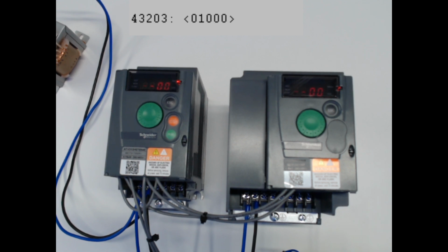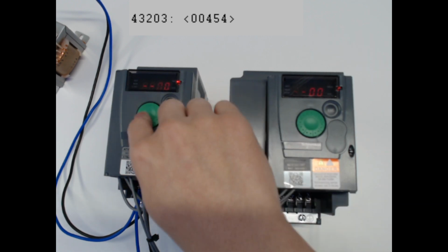Okay, so the value is a bit wonky because it is expected to have a decimal in between. For example, now I'm running at 45%. So assuming a 10 bar sensor, now my reading is at 4.5 bar. So this is a 0.01 bar resolution.